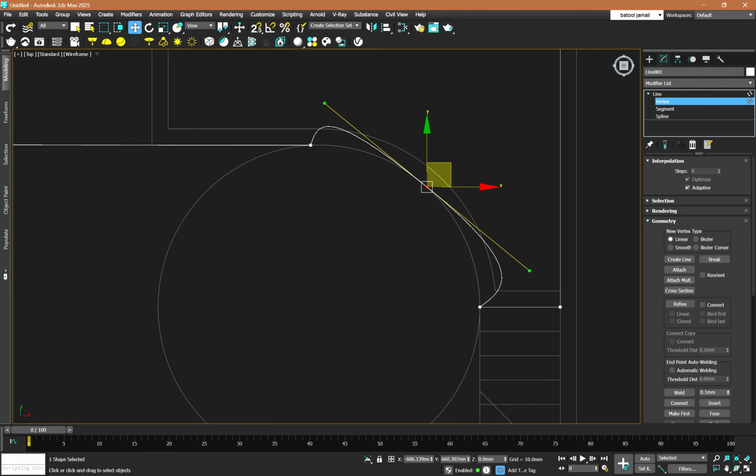If you take them further away from your vertex, the curve will be bigger. So just make sure that you are trying to get the perfect kind of curve. You can open a snap and you can move this because I'm not sure if this is in the middle or not. So once you see that both sides are almost similar, close your snap again and then make sure that this is a bit bigger. And you just continue with this until you get your curve correctly.